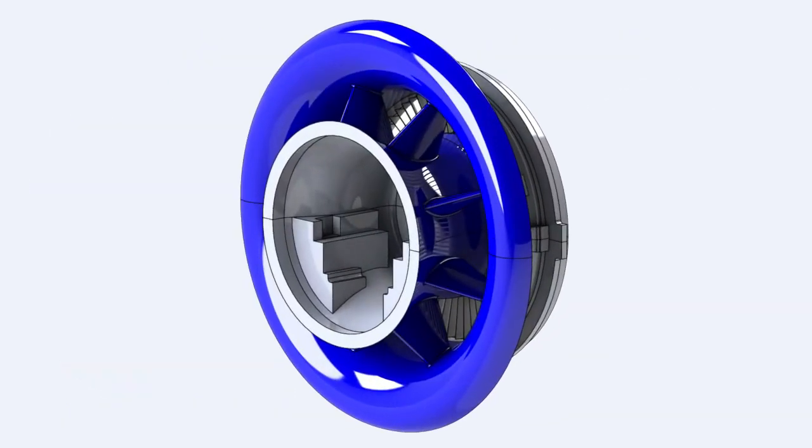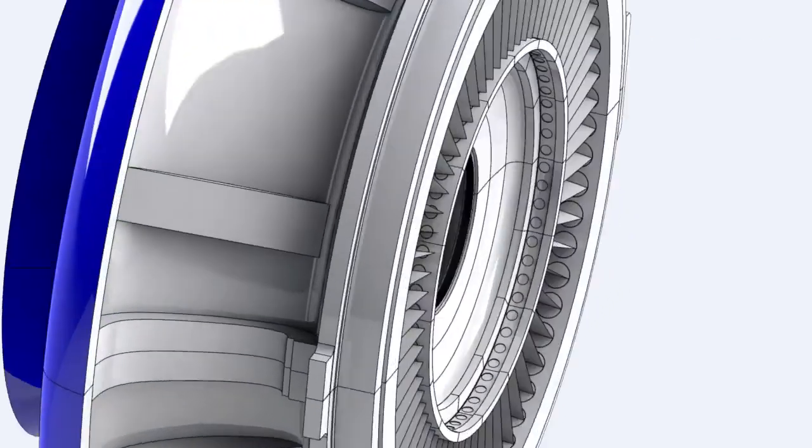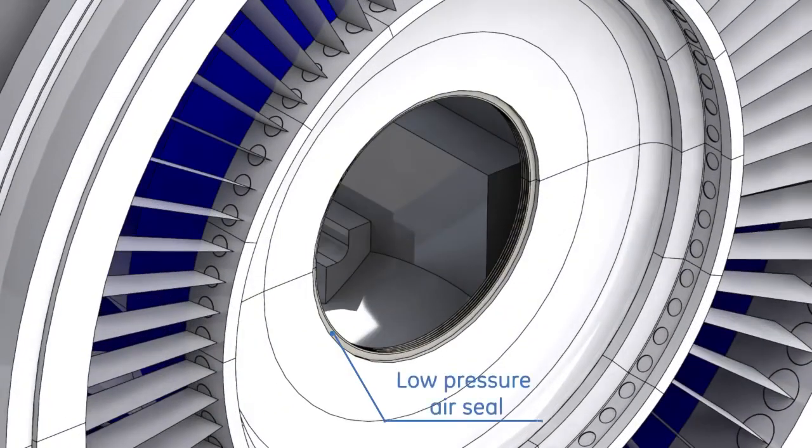The inlet casing is located at the forward end of the gas turbine. The blue painted section at the forward of the casing is called the bell mouth. The inner bell mouth is positioned to the outer bell mouth by 8 airfoil-shaped struts. The bell mouth function is to direct the air normally and uniformly to the inlet guide vanes for efficient airflow control and better inlet flow coefficient. The lower half of the bell mouth provides support for bearing number 1. A stationary labyrinth seal is installed at the aft end of the inlet casing to prevent suction of contaminants into the compressor.